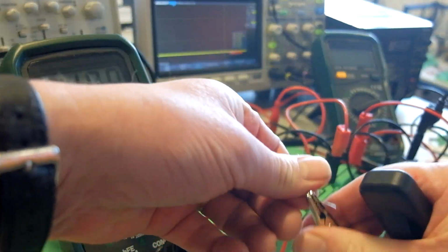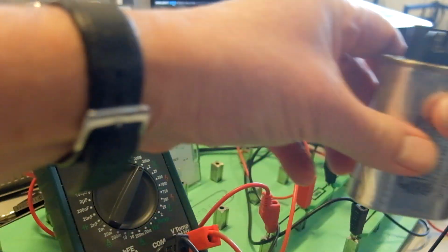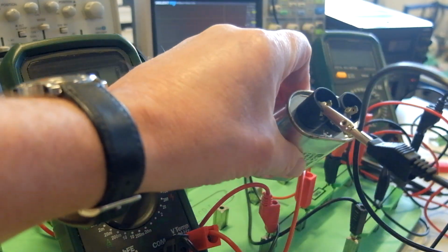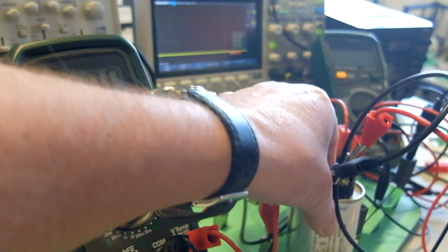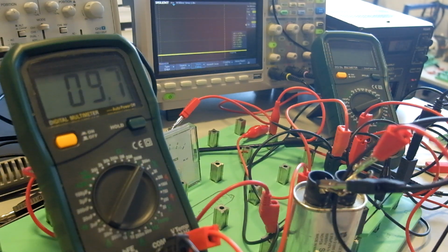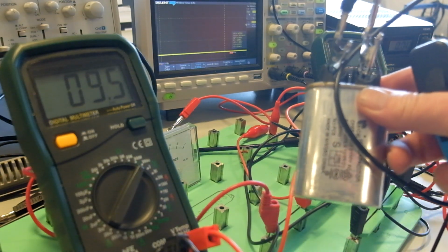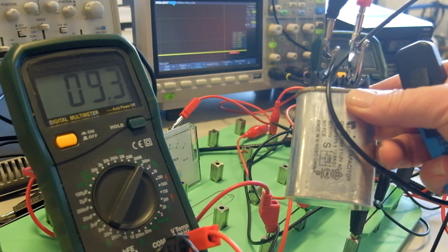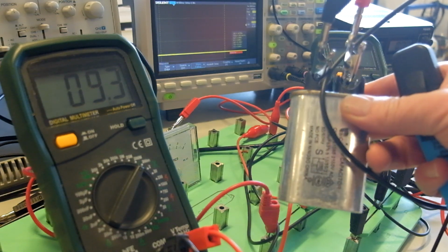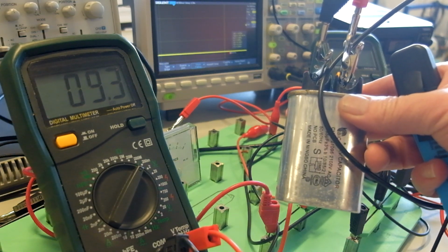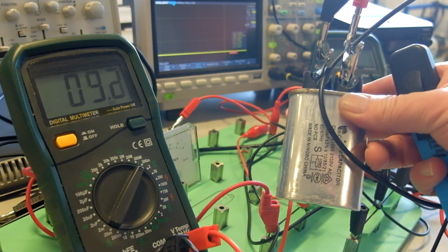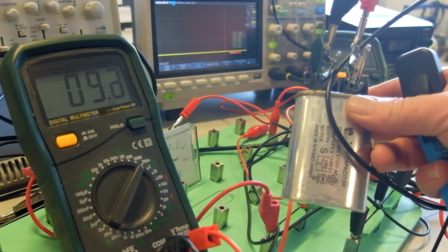What we're going to do now is use a high voltage capacitor that's been taken out of a microwave oven in a previous video. 1 microfarad capacitor here. This actual capacitor has a 10 megohm physical resistor connected in parallel so that it can be safely discharged when the power is switched off. That is not the leakage resistance of the capacitor, which is likely to be much higher.